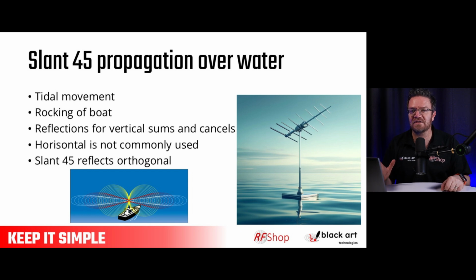One simple way is just to use polarization, because of a slant 45 signal. If something has this angle, when it reflects, the reflected wave turns in polarization. So suddenly when you are trying to pick up the signal, the main wave that you see from me to the camera, for instance, still comes through. The reflected wave turns, so your antenna is seeing the reflected wave in cross polarization.